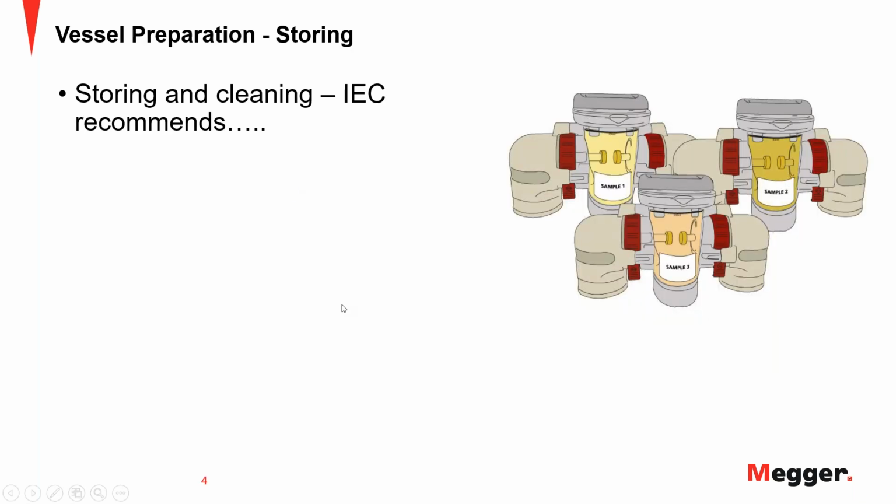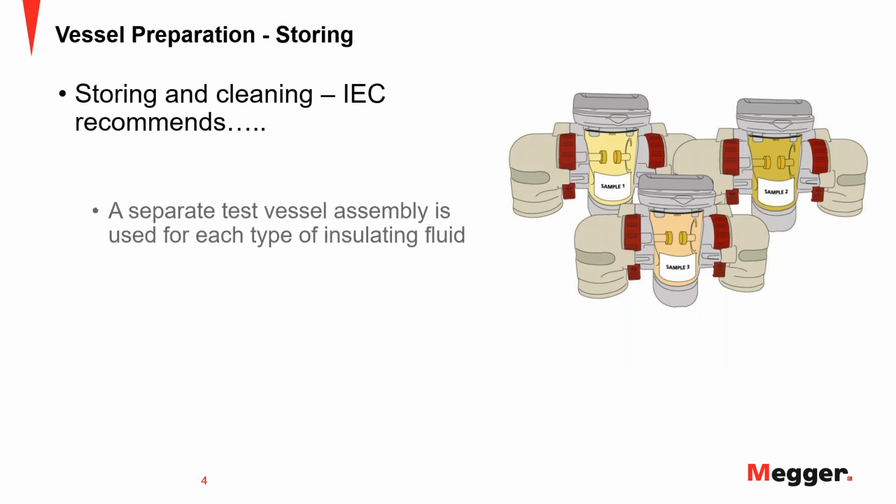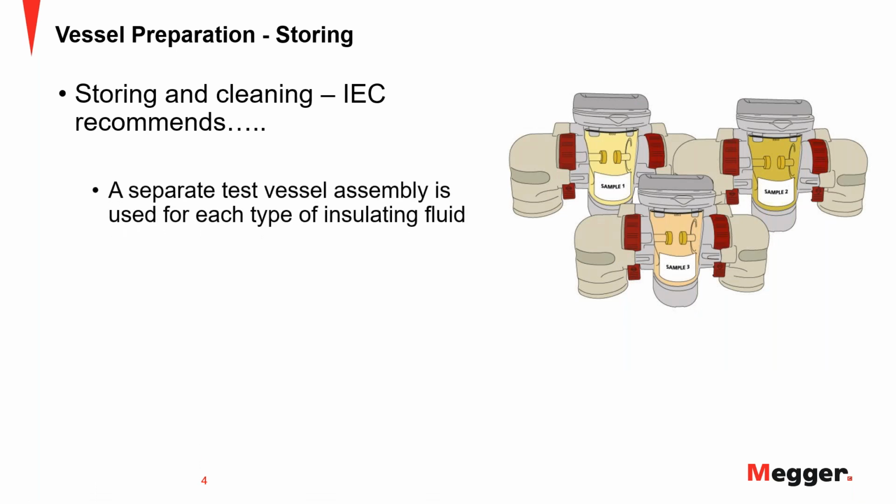Okay, so when we look at storing, IEC recommends that a separate test vessel assembly is used for each type of insulating fluid. So you try not to mix different types of insulating fluids. Say, for example, sample 1 would be a mineral oil, sample 2 could be an ester, sample 3 would be a silicon oil. So the recommendation is that you use a separate test vessel for the different types of